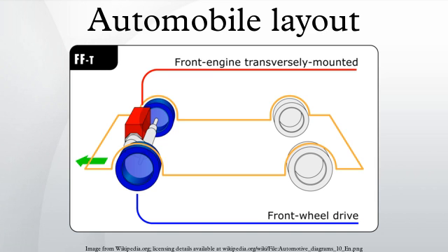Robustness. Due to geometry and packaging constraints, the universal joints attached to the wheel hub have a tendency to wear out much later than the CV joints typically used in front-wheel drive counterparts. The significantly shorter drive axles on a front-wheel drive car cause the joint to flex through a much wider degree of motion, compounded by additional stress and angles of steering, while the CV joints of a rear-wheel drive car regularly see angles and wear of less than half that of front-wheel drive vehicles.